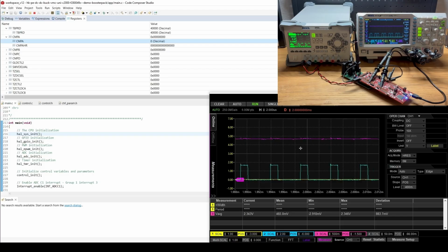This demonstrates why CPU load is so important in real-time digital control systems. A converter may initially appear to operate normally even though the controller has already stopped executing correctly. Only when the operating conditions change does the problem become immediately visible. In practice, engineers often start debugging by checking whether the control interrupt is actually executing. If the interrupt is no longer running, excessive CPU load is one possible cause that should be investigated.